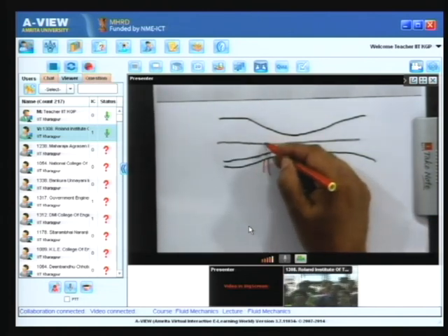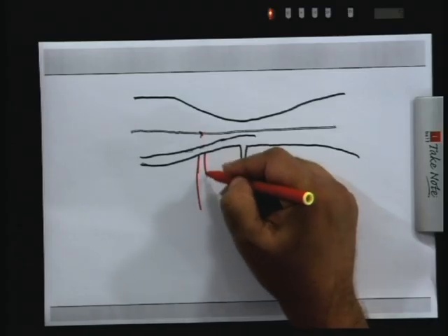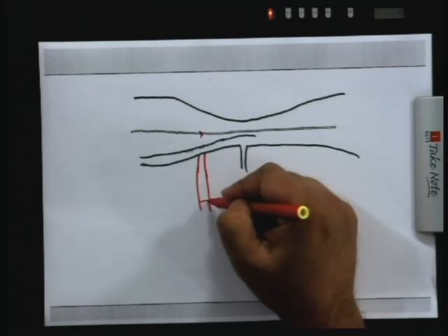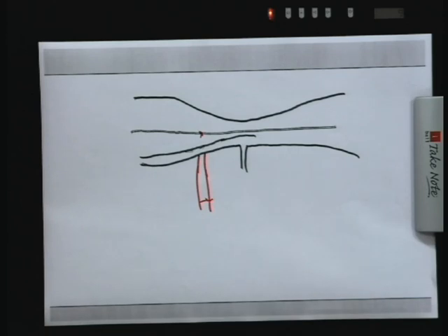if you want to difference the pressure between this point and, let us say, suppose this is a manometer liquid level over here and this point, you have to also account for the centrifugal term due to the curvature of the streamlines, which you do not know, so you cannot estimate it.